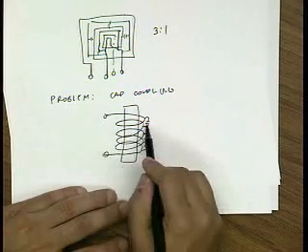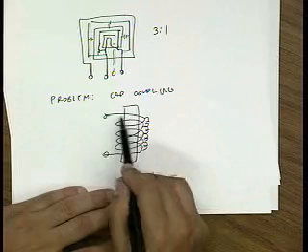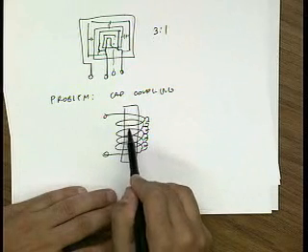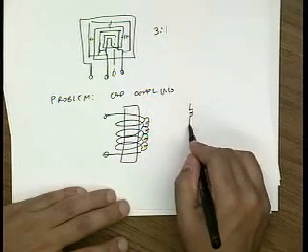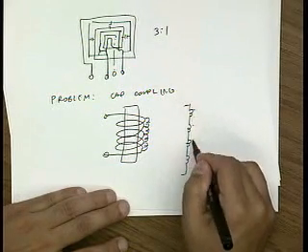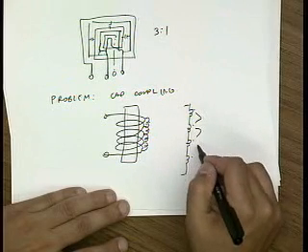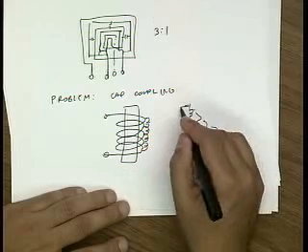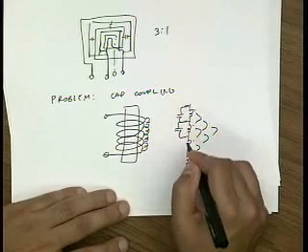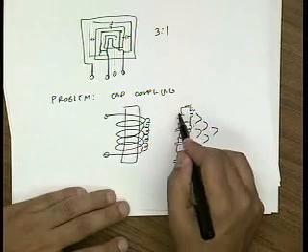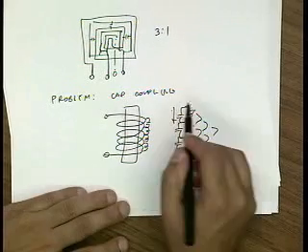At really low frequencies, this capacitance doesn't do anything because this is all shorted. But at high frequency, you can think of these turns as being basically loop inductors which are coupled together. And there's capacitance going like that. So at really high frequency, the potential, let's say from here to here, is different, and so current can flow in these capacitors.